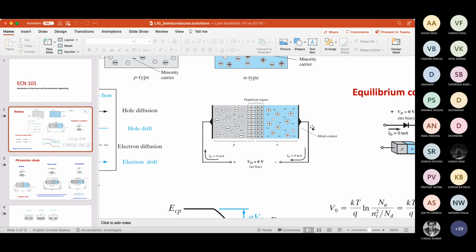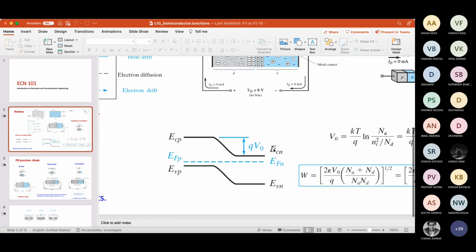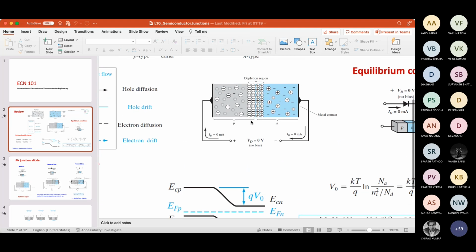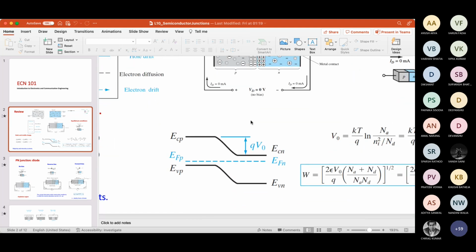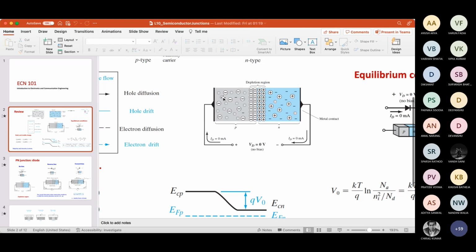So that's another argument. But at the core of it, from the thermodynamics of the carriers, the reason is that the Fermi level is constant throughout the device. So that's why any external voltage cannot be visible across this PN junction. That is the more fundamental physics point of view. From an instrumentation point of view, the contact potential will neutralize this depletion region's inbuilt potential.